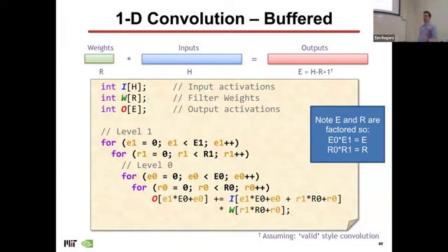You'll find that tiling is probably one of the most useful things you can do in all of computer systems, because usually you end up being bound by memory, and these accelerators are no exception. Okay, so there are examples of accelerators that have these intermediate buffers, and then you basically have to make sure that you map things to tile appropriately.